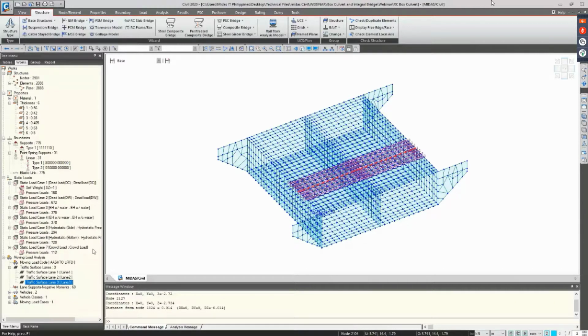So if you are analyzing a box culvert two-dimensionally, there is a separate provision for that in our code, the AASHTO code as well, that you need to consider. Also, if there is soil above your box culvert, you also need to have another provision for that because the distribution of the loads from the top of your pavement going to your culvert will be different.